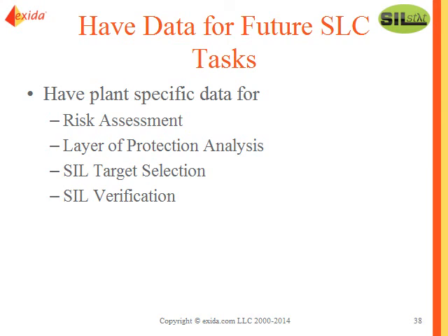If you look at failure mode effect and diagnostic analysis data for specific equipment items, it's an average worst-case environment, and it's expected that for a majority of all applications around the world, that data is applicable. Well, you may have a very benign process, and maybe you can justify an order of magnitude less, or you have a very harsh environment, and you're operating the equipment on the edge of its specifications, and maybe your failure rates are a bit higher.